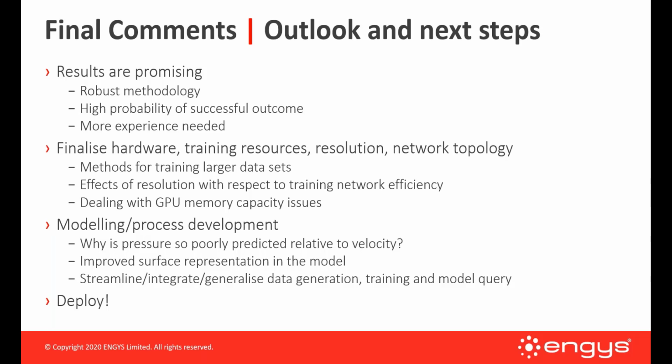Of course, we also have to try and get high fidelity data for the 3D models, which is more challenging because running an LES or a DES calculation on a full vehicle can take several days. These small 2D cases take a few minutes to run, and that of course will increase. We have means to do that, but they're still being developed, and we are not confident yet what the outcomes will be.